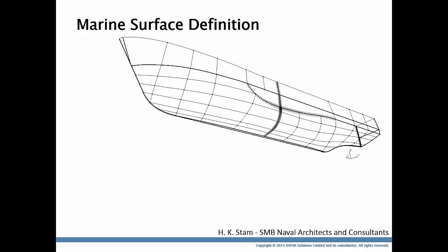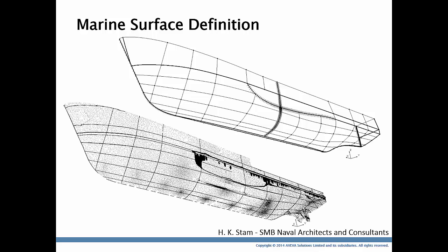Crossing over to the laser scan, one of the nice benefits is that we can section the laser cloud exactly in the same place where the curves are going to be. So this means that we can extract the data where we put these curves very quickly and very easily. In this respect, what we're looking at is intersecting the laser cloud with a plane and then purely doing a curve fitting exercise.